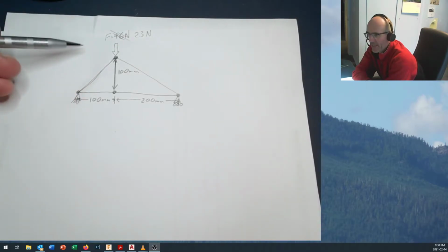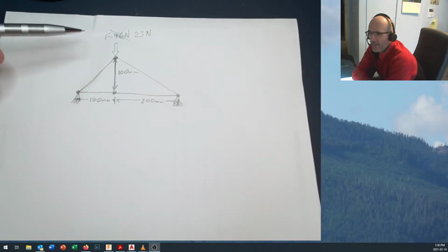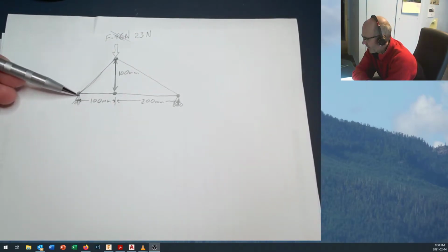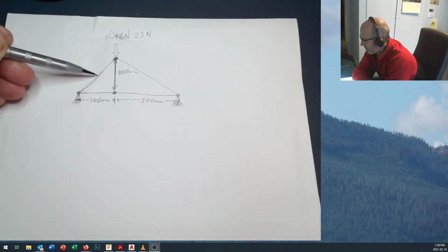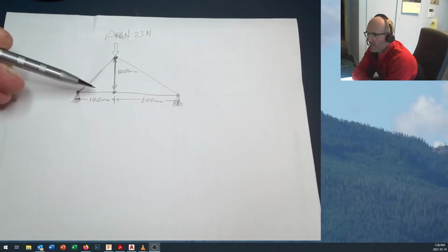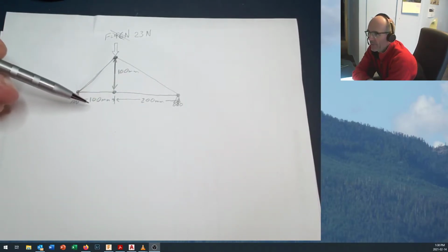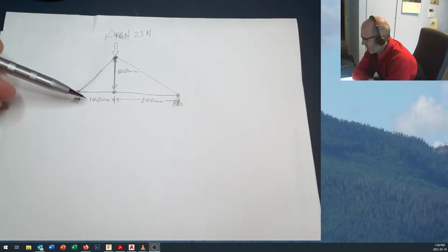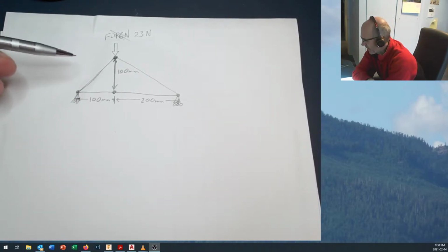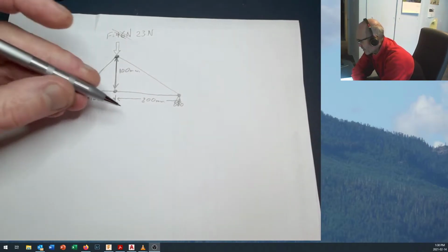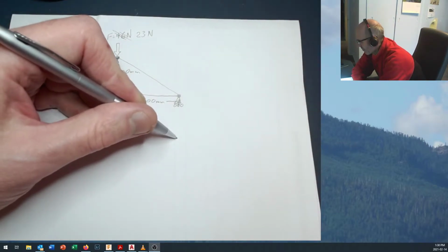You should be able to take a truss like this and calculate the reaction loads at each of the nodes and which members are in compression, which members are in tension, and the amount of compressive and tensile force in each of the members. This is a pretty simple one, similar to something that we did a while back. And remember that it's going to start out by balancing the moments.